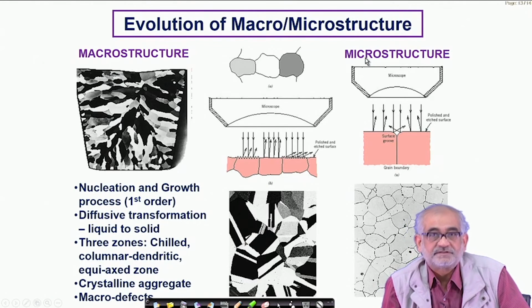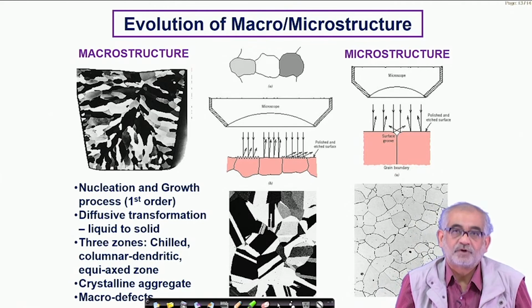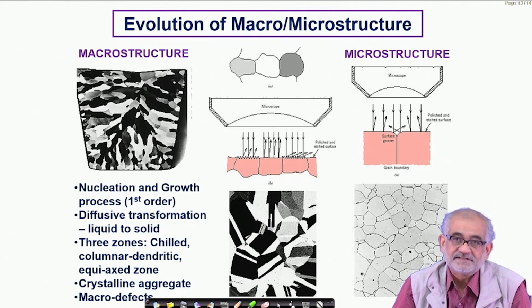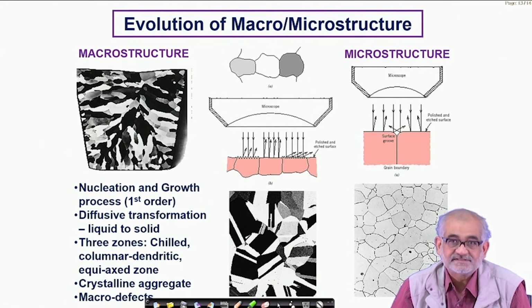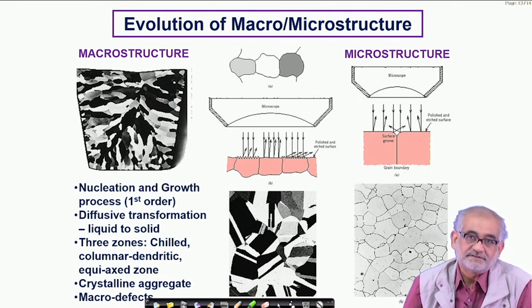But the metallurgists and the materials engineers understand the worth of microstructure, which actually is, as I said, a composite or a complex body of knowledge comprising the shape, size, identity, volume fraction, and orientation and distribution of the various phases that make up the solid.